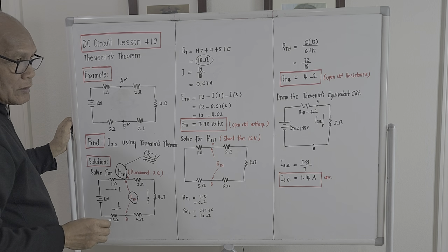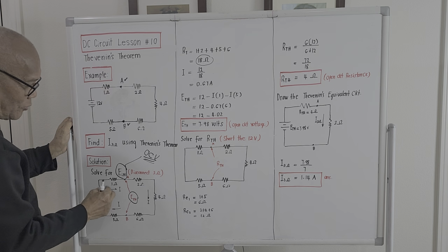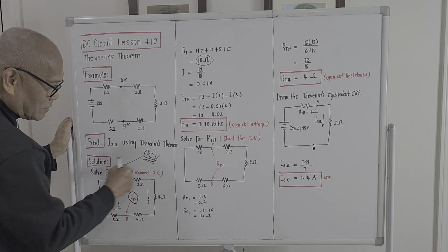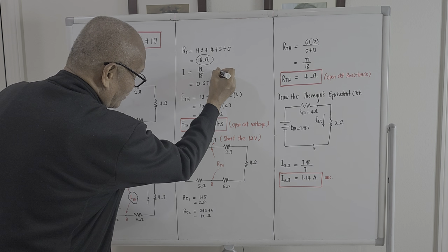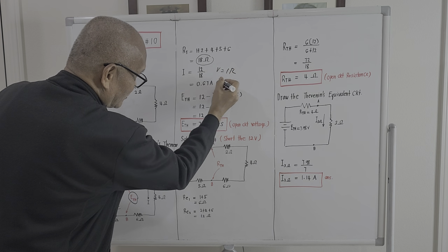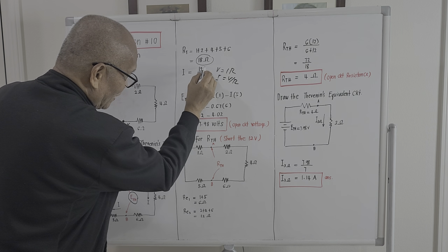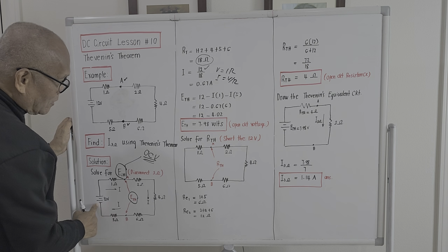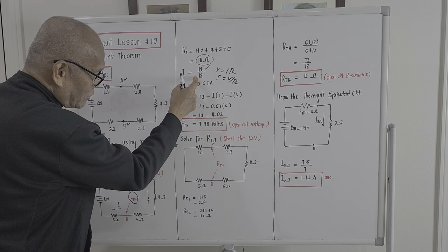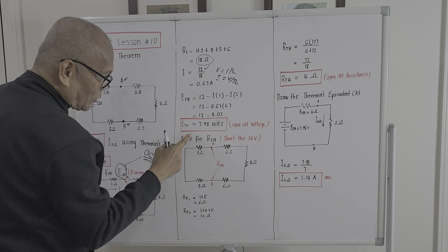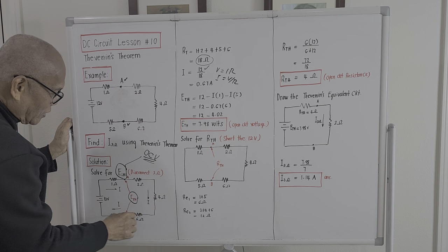Okay? So if we know the total resistance and we know the applied voltage of 12 volts, we could compute for the circulating current. By using voltage equals IR, I will be equal to voltage over R. The applied voltage will be 12, and the summation of these 5 resistances is actually 18. That will be over 18. So we could compute for the circulating current: 0.67 amperes. So we now know the circulating current.